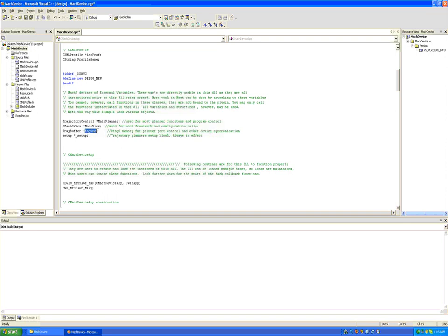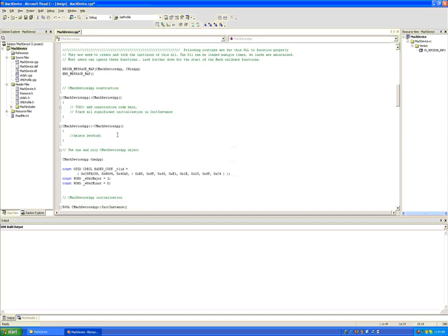Changing variables in Engine can trigger movement, can get direct access to the ring 0 ports and pins and various things inside your kernel. And then there is setup, _setup, which is a pointer to the trajectory planner, RS-274 information, and various configuration data of your trajectory planner. Most of the primary code here you shouldn't touch. You can add message maps if you wish for your plugin.